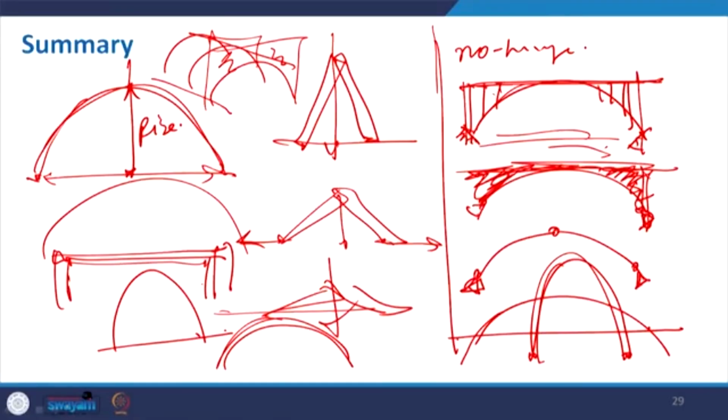So there is no such constraint on the material, and this has an advantage over a simple beam column structure, but proper geometry must be maintained. The shuttering of the arch is very crucial, whereas in a frame structure it is very easy to support, but for this you have to support it with proper care. The centering of the arch, the shuttering, the temporary structure built to make the arch form, and the symmetry to be maintained are very critical, otherwise you will not get the advantage of the structural form.